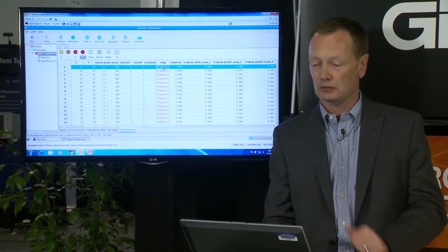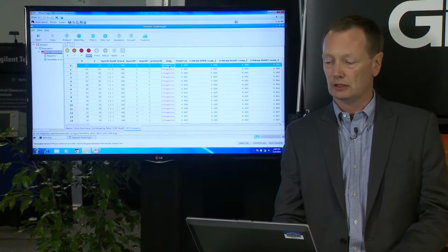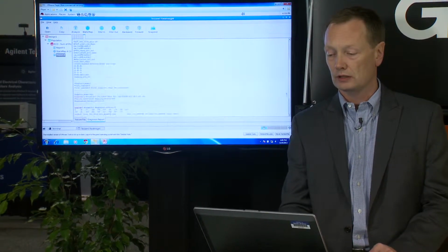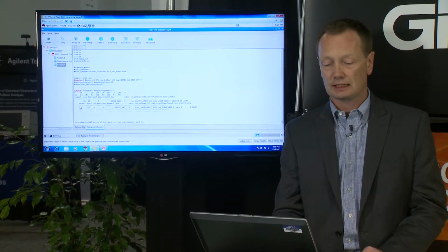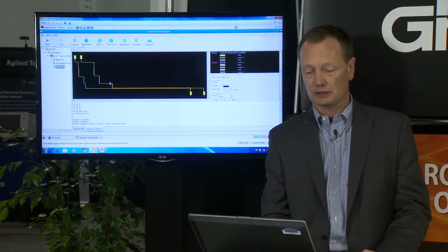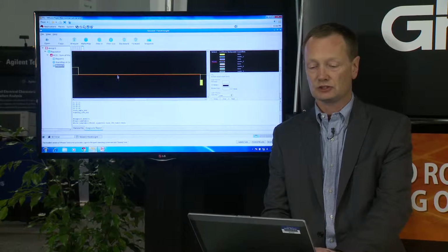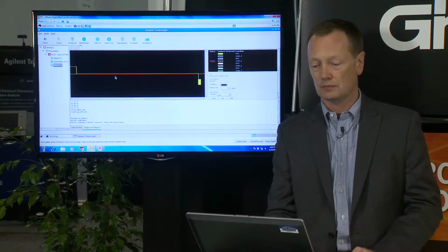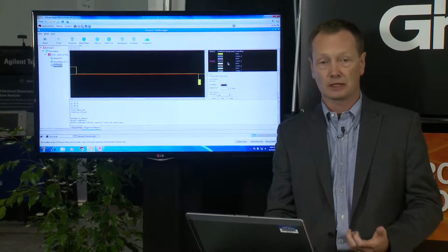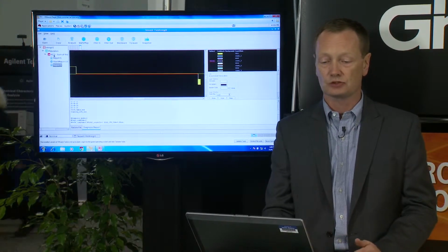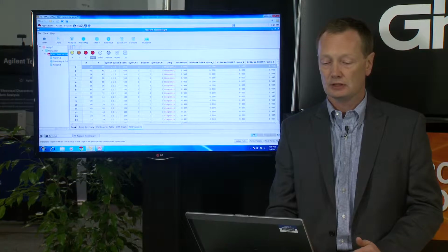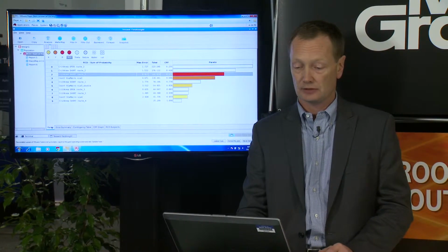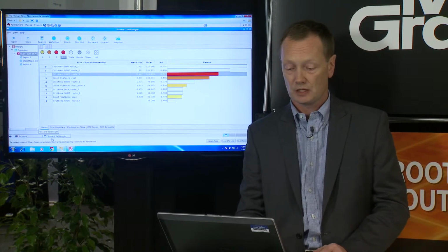But now, looking at the metal 3 shorts, I can again look at the diagnosis report for one of these devices, and I can look at this in the layout viewer and find the location where these 2 nets are most likely bridged together in metal 3. So again, I can use this to both find the defect distribution and also find the best candidates for FA.